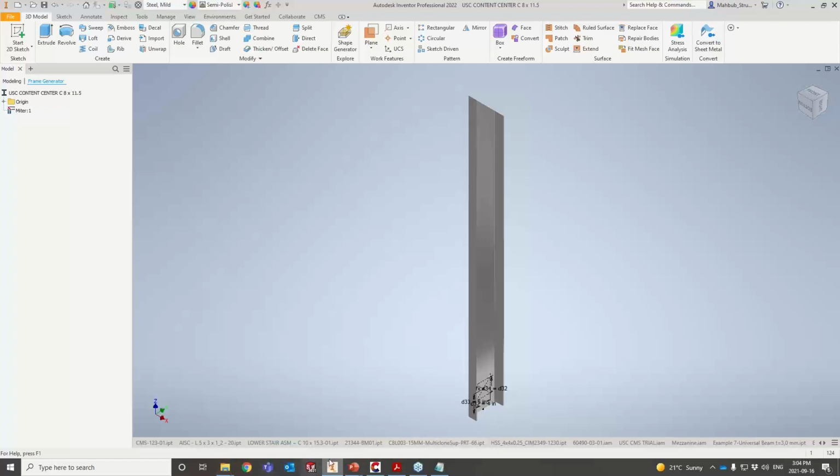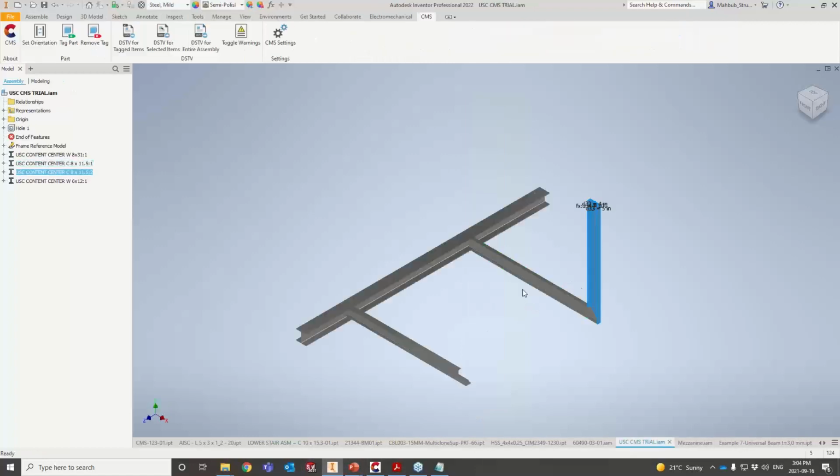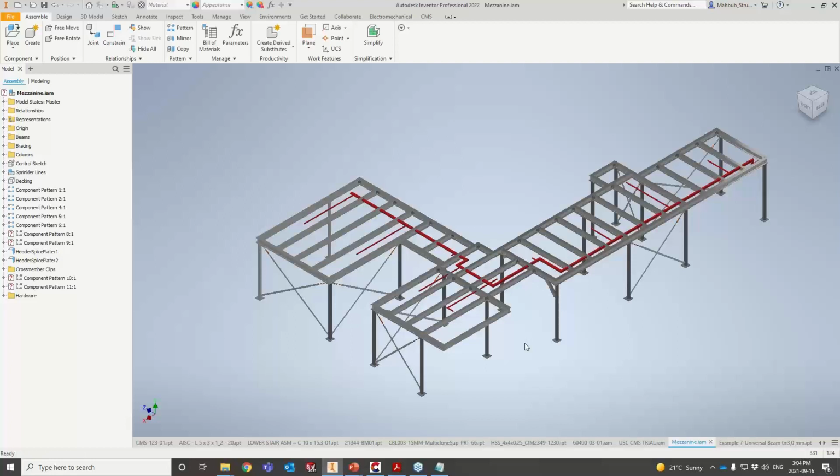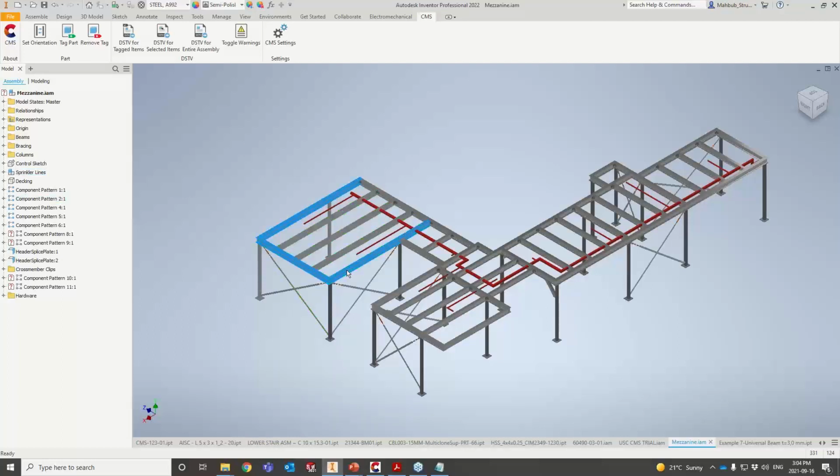Okay, so that assembly is an easy demonstration that you can also tag members, and from tagging you can create an NC1 file, right? So there's another example that helps. If you have an assembly where you're missing some reference parts, but you have access to a few members, you can just tag. I can select the members that I want to convert to NC1. So selecting members and creating an NC1 file from there is also possible.